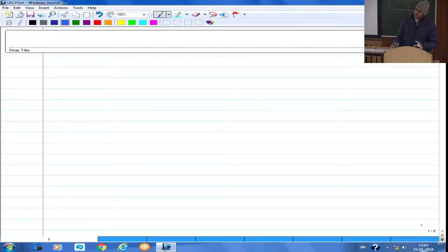So then we have to choose an element which has provision for both axial deformation as well as bending deformation. When we discuss the frame element, at that time we will talk about that. As of now, whatever we did, we can model only problems where there is only force along the length of the member, axial force. Okay, is there any other question?